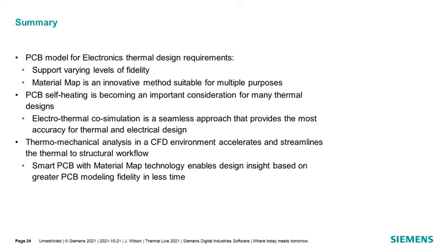I also pointed out that PCB self-heating is becoming an important consideration for many thermal designs. I quickly looked at how you could set up a Joule heating simulation in SimCenter FlowTherm XT, but that's not really a scalable approach for thermal designs that have complex nets, and many current sources and voltages that you would have to apply. Those are better applied in a power integrity tool.